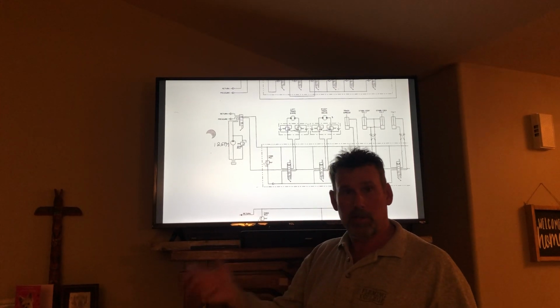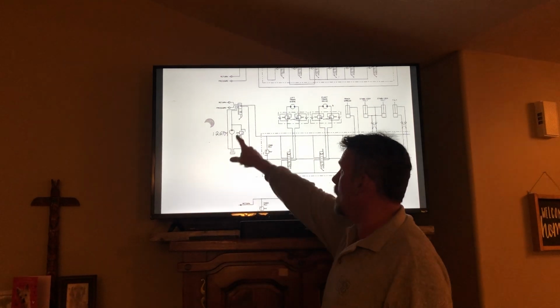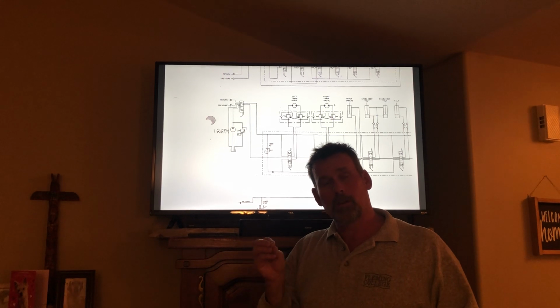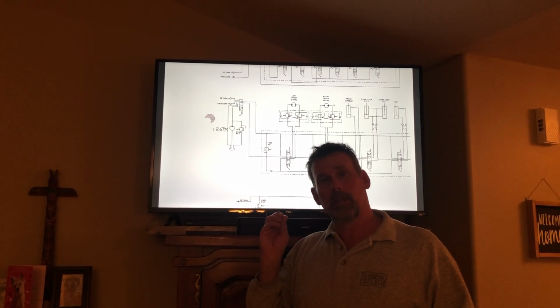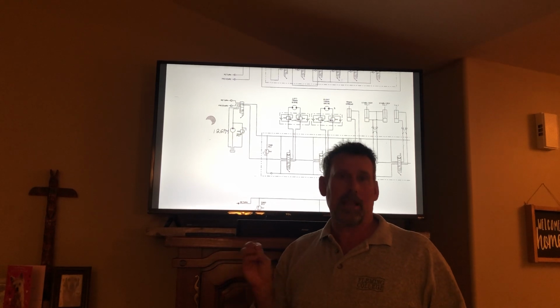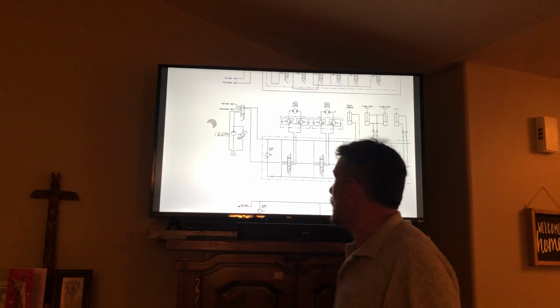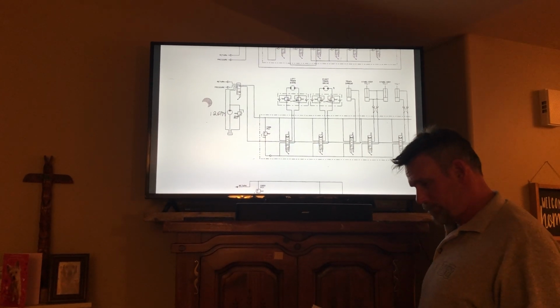So it's positive displacement, it can push into a pressurized system. And it's fixed displacement, meaning that if it's turning at one constant RPM, like an electric motor would turn it, then it will give a constant gallons per minute, constant flow rate all the time. Okay. So fixed displacement, positive displacement out of that pump.